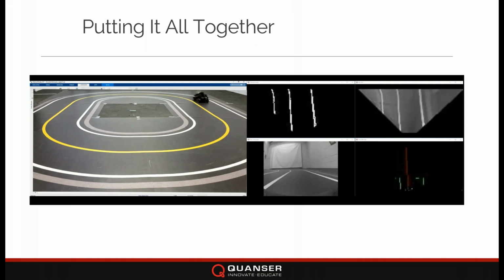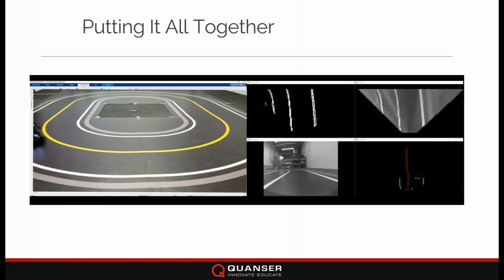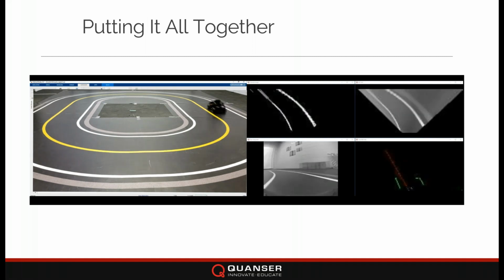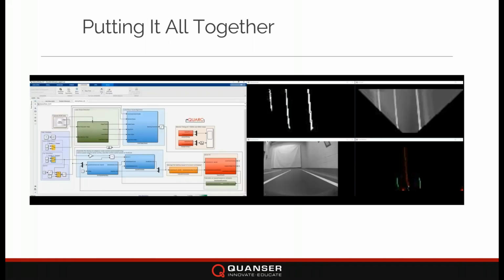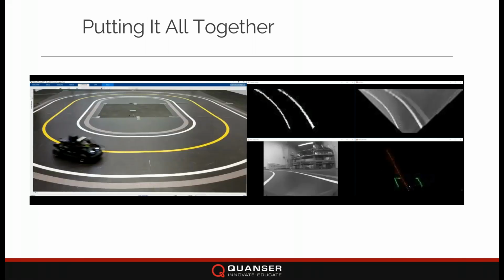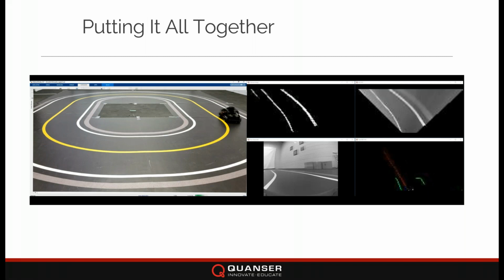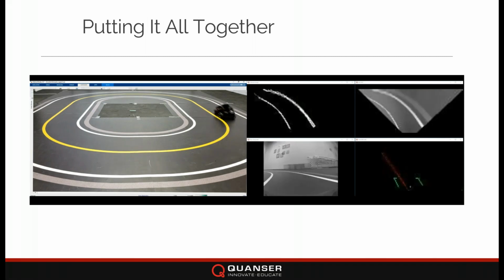So I can see I've got smooth control of where my car needs to be. Going faster just means that I don't have the full ability to process the image fast enough, and so I would leave the lane, and that's how experimentally I'm able to find what the maximum speed of my car is. But this more or less goes to show how we can use the bird's eye view as a lane keeping tool in order for me to develop a more complicated lane keeping algorithm if I'd like.